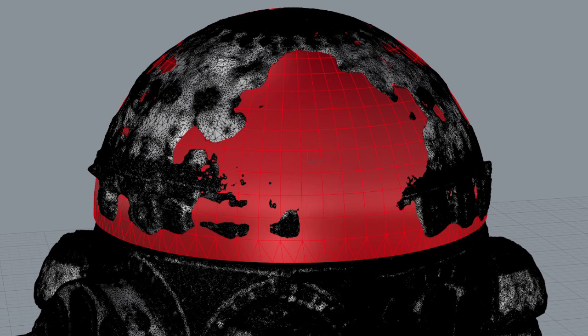The other thing, in addition to reducing the geometry, is also reducing the texture maps of the model itself. On the left side, you'll see one of the raw texture files that comes out of photogrammetry. If you've ever dug into a photogrammetry model, you'll probably recognize the very haphazard quilt work that is one of those texture maps. It's very perspective-based and kind of random. But then on the right was the remastered file that our GA processed.